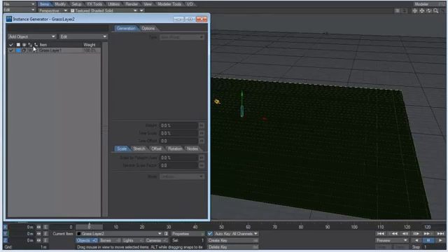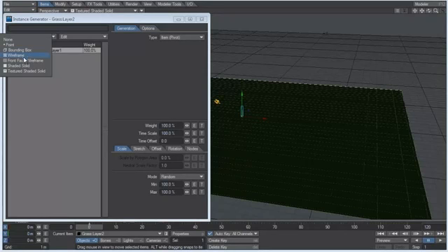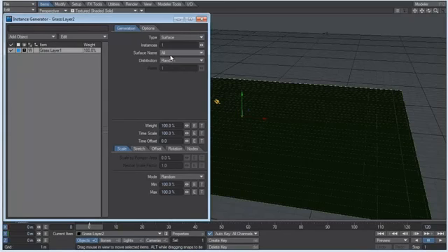There we go. Okay, so if you come to this eyeball here and select that, you can see that you can choose from various types of settings. So let's just switch to texture shaded solid, and the item type is going to be surface because we want our grass blade instances to be conformed to the surface of our ground plane. So as I start scrubbing through instances, you can see that they're being populated.